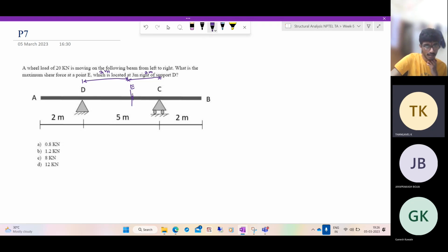As usual, let us release the shear resistance at this point. Right? There's a shear force here. Let us release it and apply the shear force. So left span down is positive, right span up is positive. So if you apply this, you see it's again like a seesaw. It is supported at one point. How will it deform? It will go down like this, right? And on this span, it will go like this.